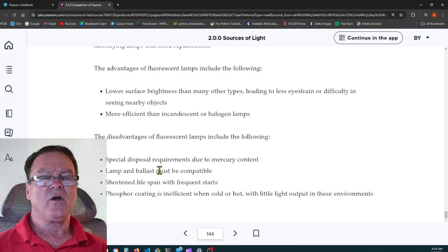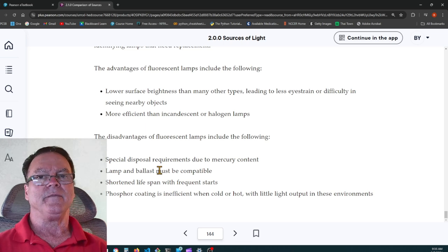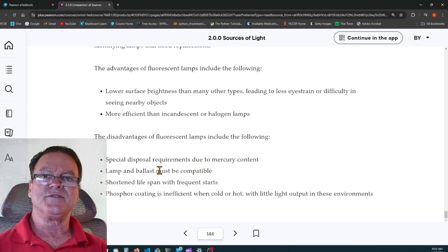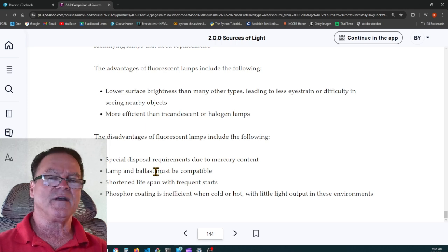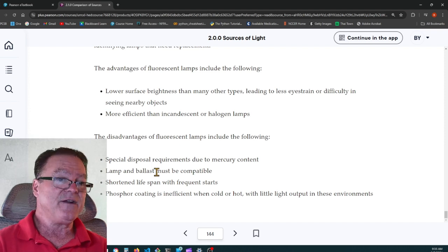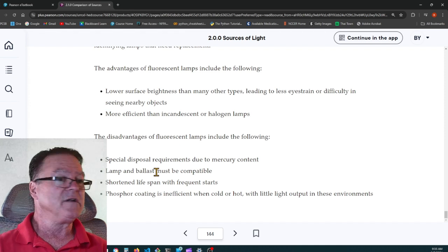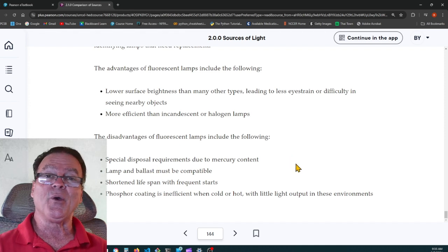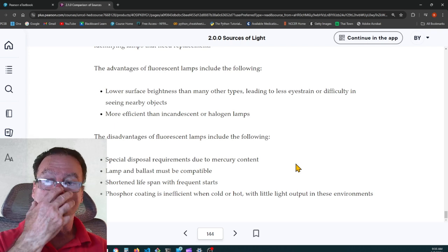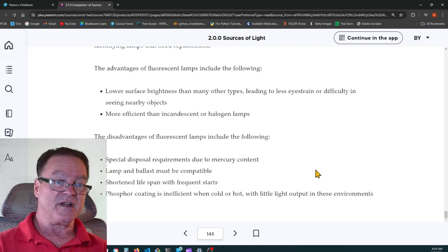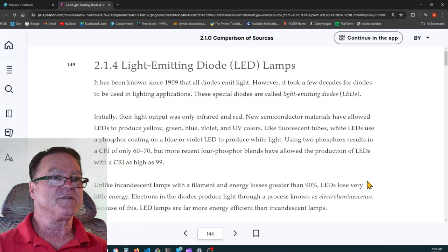These things are a health hazard. Don't play with them. I see these TikTok or YouTube videos where they're playing Darth Vader and they've got the fluorescent tubes and they're smacking them against each other and they're in a shower of glass and phosphorus and mercury vapor. It's like, man, you can't imagine how stupid that is. These guys, they don't know what they're doing. They think it's hilarious. Don't do it. Dispose of them properly. Wear at least a particle mask when you're disposing of them. And don't use them as a lightsaber.